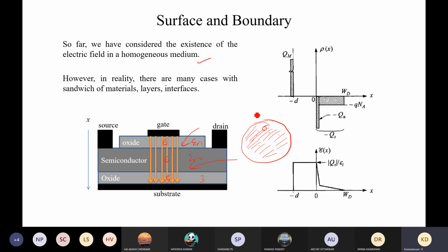And because of this high conductivity, when an electric field is hitting upon that, some amount of electric field will be reflected back. Some amount of electric field will go inside. And this penetration depth we can even calculate. Interestingly, this is applicable for one particular frequency. For another frequency, another depth will be there. So using this property, we can study the conductivity of a particular material. And in order to get a huge amount of reflection, you need very high conductivity.